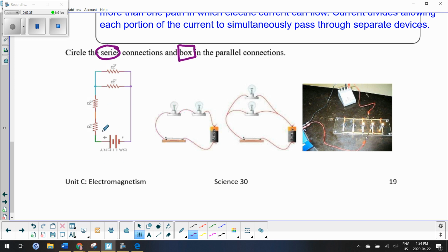Looking at this diagram, this looks kind of Greek. This is what a circuit diagram would actually look like, which I'm going to explain a little bit later. This is representing your battery pack. The short line represents the negative terminal, and the long line is the positive. So I have one battery, I guess you could say, and then another. Electricity is going to flow out the negative, like I taught you last time, and move to the positive, so it's going to come back around.